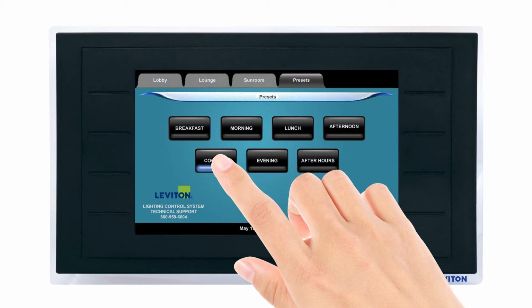Again, the new look will fade up over a 2-minute time span so as not to implement an abrupt lighting change. It will initially appear as if the lights are not changing as the system starts the fading sequence. If you would like the system to jump to the next preset without the 2-minute fade time, double tap the button and the lighting for that specific space will immediately change to your selected preset. This is not recommended when the public spaces are occupied by guests.